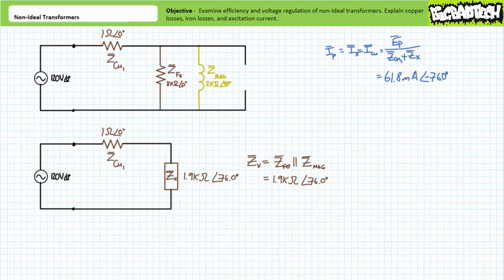Now, before you freak out about this, take note of the large lagging phase angle, characteristic of a reactive element that merely exchanges reactive power with the source and largely doesn't consume real power. This being said, it's not lagging by a full 90 degrees. We might expect consumption of a small amount of real power.